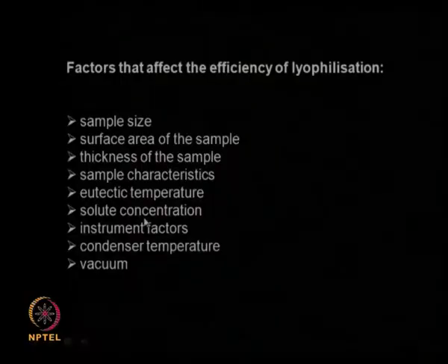Solute concentration, how much solute is present in water. Then the instrument factors, what are the various instruments which you are using. Then the condenser temperature, you are going to ultimately take out the vapor and condense it again. So what is the temperature, and how much vacuum you are applying. All these factors affect the lyophilization process.